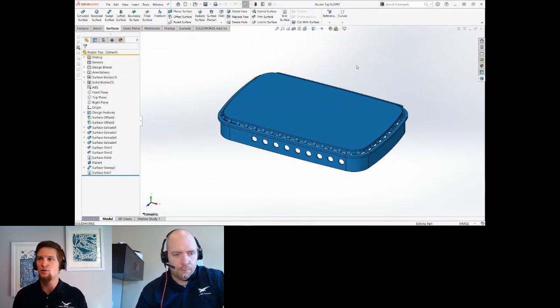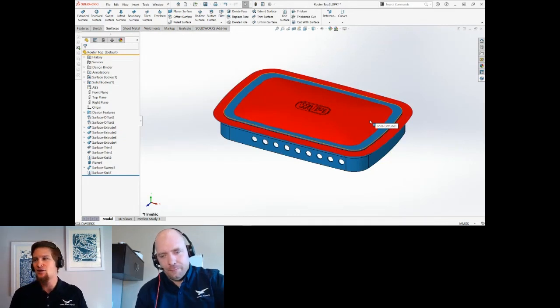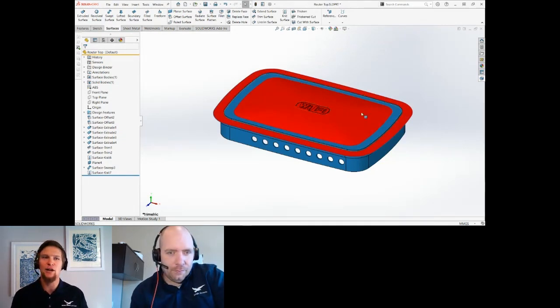So what's a quick little shortcut to bring it back? Garrett knows the trick. Shift tab, man. You got it. Tab, shift tab. Those are a couple of quick things that if you don't use them, start exploring them, right? I just hover my cursor where that body used to be, hold down shift tab, and we can run right into it and bring it back to visibility.